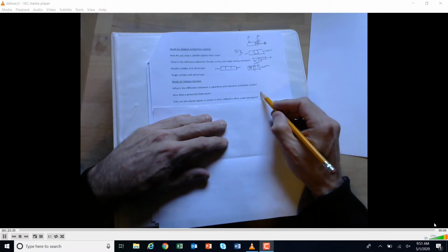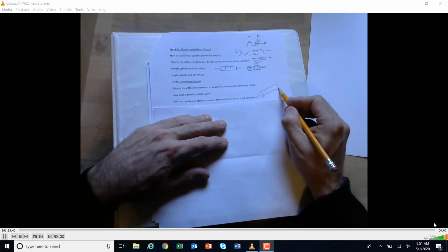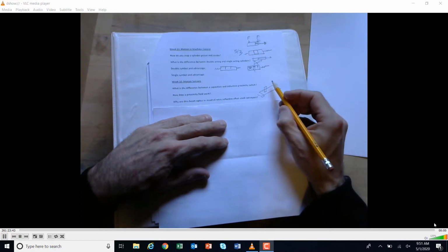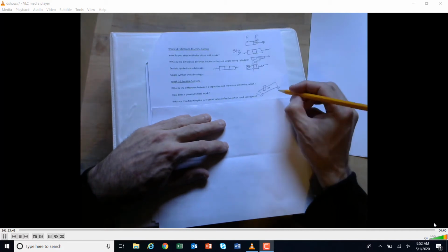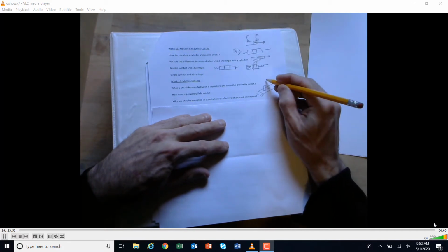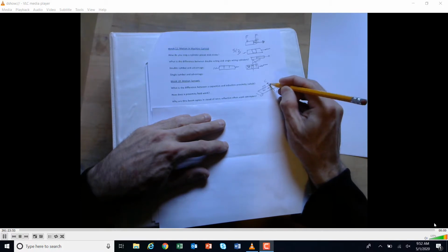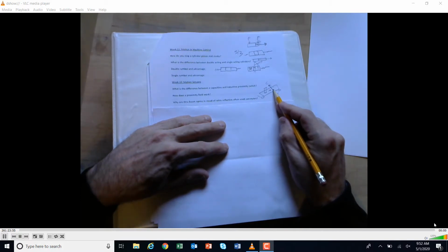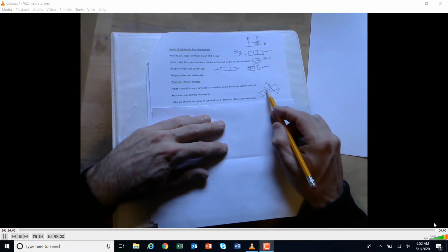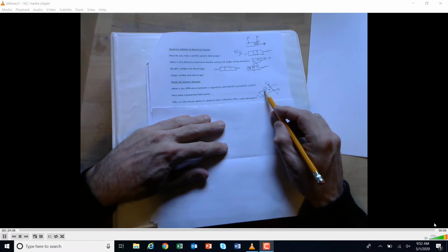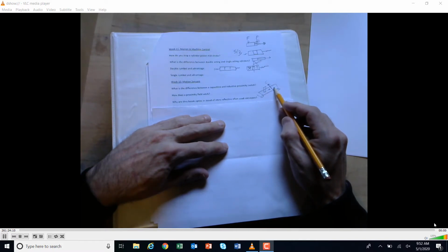Well, on a conveyor, you would have a part rolling down this conveyor. Let's put something on there, going this way. So a through beam, if you just want to count it, that's pretty easy to do. You would have an emitter here and a collector here, and you just shoot a beam of light across there. And then this will break that beam pretty simply. It doesn't matter what your working environment is here, if this is greasy or if there's something kind of in the way or not. I mean, this is going to absolutely break it, and then it's going to open it up again.